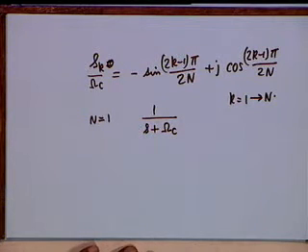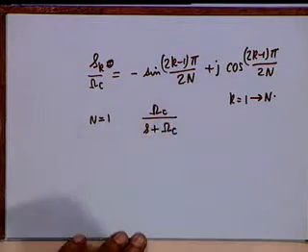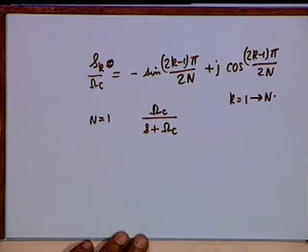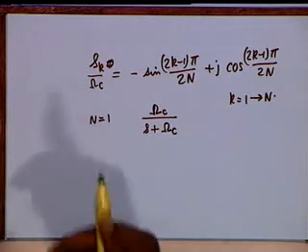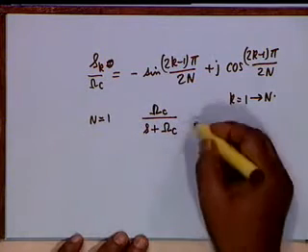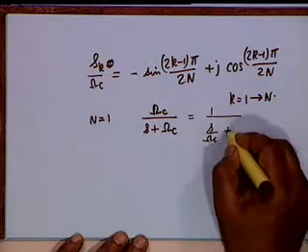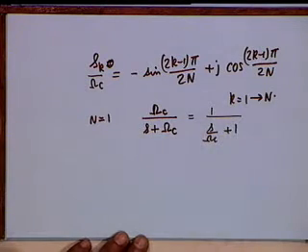Not quite. The numerator shall be omega c. You remember, for the transfer function the magnitude is normalized to 1 at omega equal to 0. In order to make it 1, we make the numerator omega c, or we can write it as 1 by (s by omega c plus 1). Agreed?